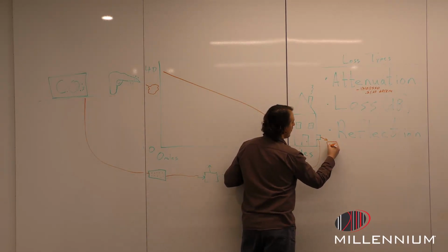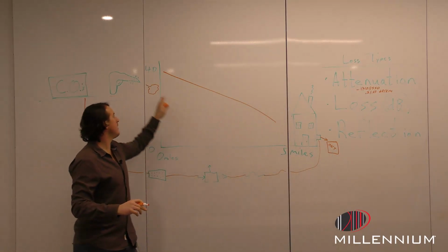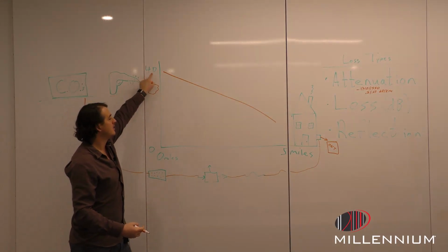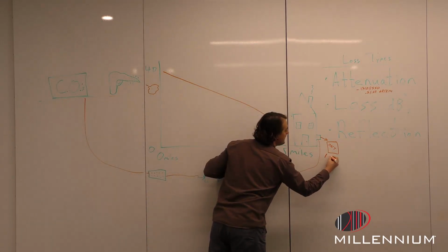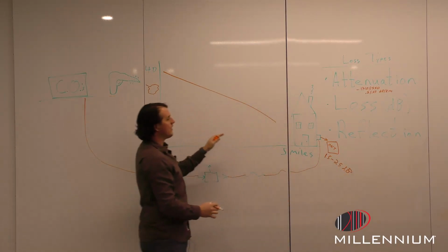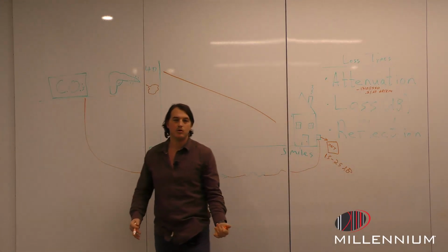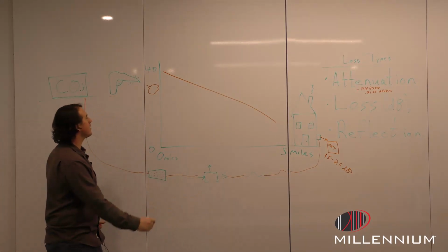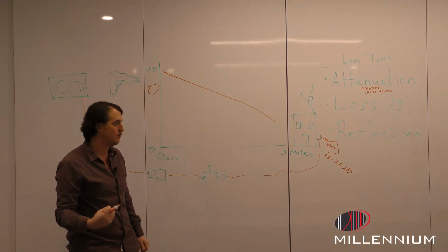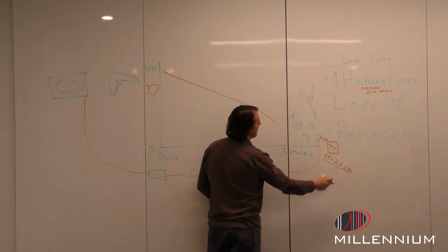That device is going to say, hey, I can only accept spitballs if they come to me at a certain power. A lot of times the range on these might be 15 to 25 decibels. So if a spitball gets to this house at 26 decibels, there's no internet. It doesn't matter if this is a 1 gig circuit or a 100 gig circuit. It's not about bandwidth. It's about the light level or the power that it's able to accept.